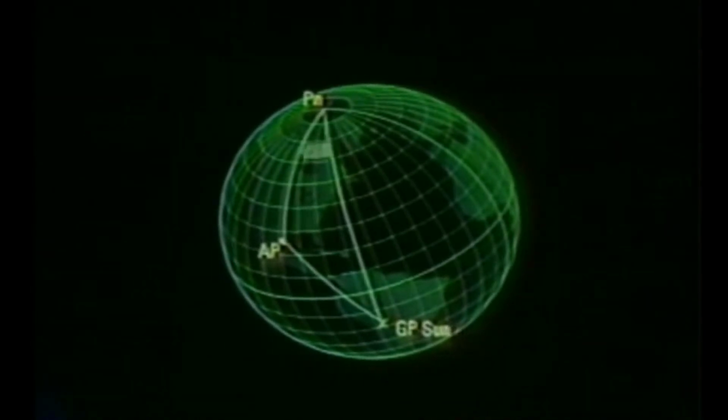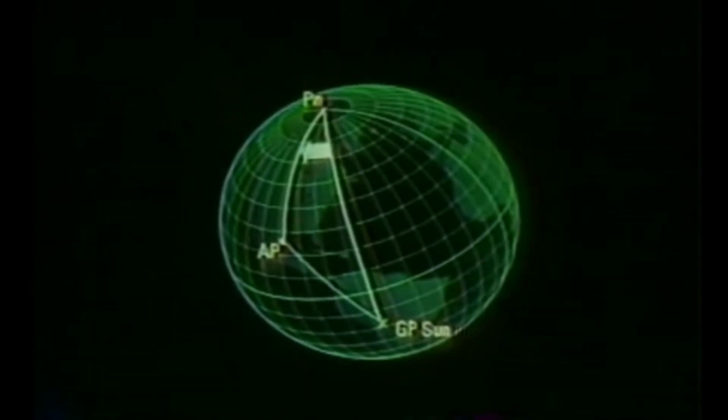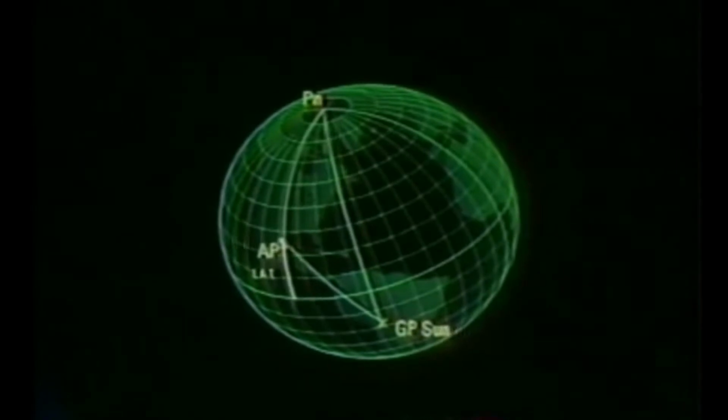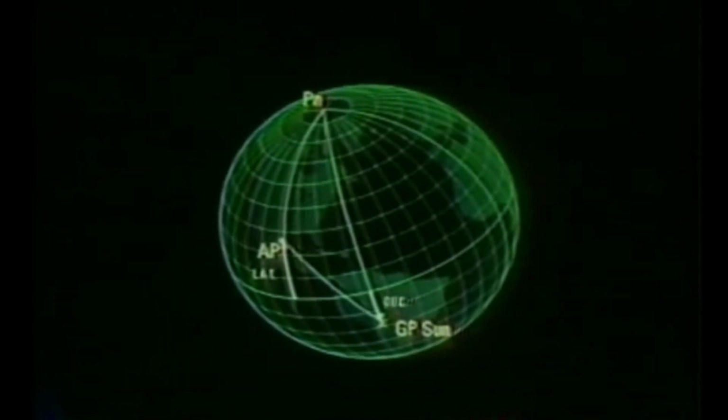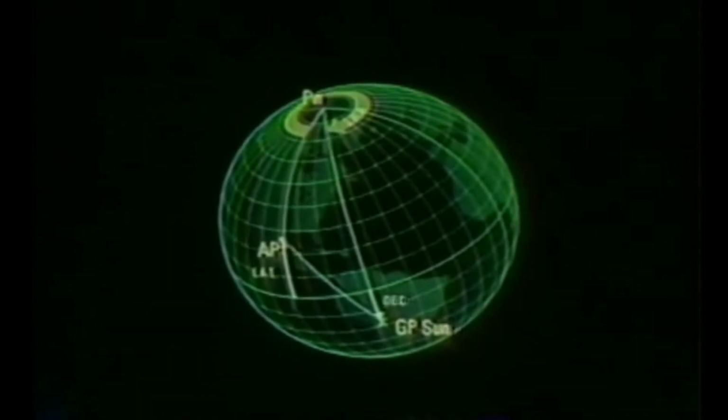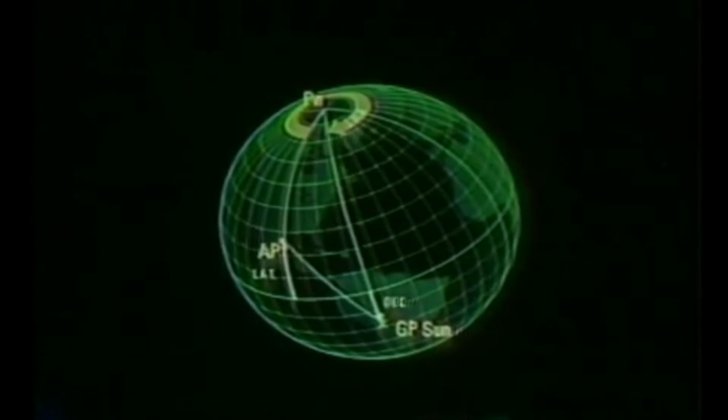In theory, if you know two sides and the included angle, you can compute the other side and angles. The mathematics are done for you. All you need to know is the latitude of your assumed position, the declination of the observed celestial body, and the local hour angle of the celestial body. Determining LHA is the tricky part of the problem solving.